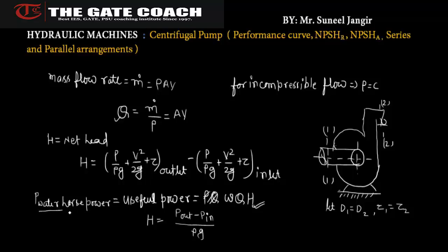Now, this term water horsepower, again I'm saying it doesn't matter which type of fluid is flowing, whether it is water or some other fluid, every time we define this as water horsepower. Also it doesn't matter what the units of this power are, in every case we will define it as horsepower. So it's not depending on what type of fluid and it's not depending on what type of unit of power. Every time this useful power delivered to the fluid by the pump is traditionally termed water horsepower.